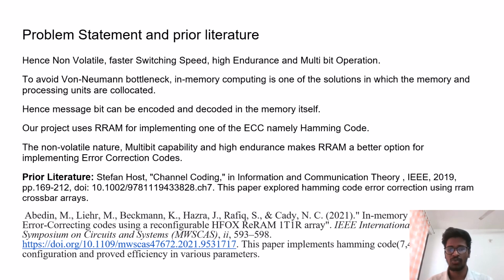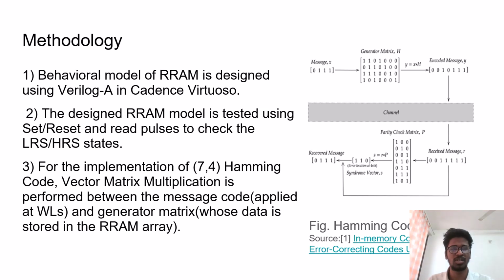So, in our project, we are using RRAM for error correcting code. Why we are using it: it is non-volatile, which means it retains data when the power is off. It supports multi-bit storage and has high endurance, making it suitable for repeated read and write operations. Methodology.